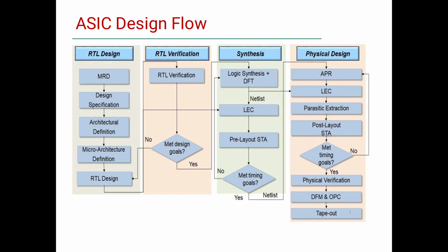Next, the pre-layout STA, static timing analysis. If the timing is met, the synthesis is done. If not met, again the same process of RTL design will be carried out. Next comes the physical design. Automatic placement and routing application starts here.